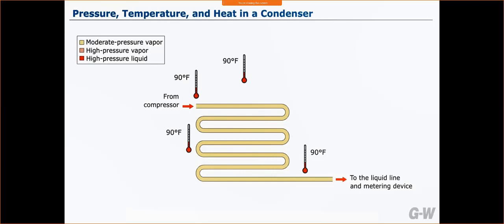One way of being able to dissipate heat quickly, and what they're starting to do, is they're trying to make the condenser units bigger, all right? So we have a same volume unit or a cooling capacity, so we'll say a 3-ton unit. Well, the 3-ton unit, when it gets really energy efficient, it's almost twice or 3 times the size of a traditional unit. And the reason being is, if I have a larger surface area, I can expel more heat without really adding more refrigerant or changing any other dynamics. And so that's what the manufacturers are starting to do.